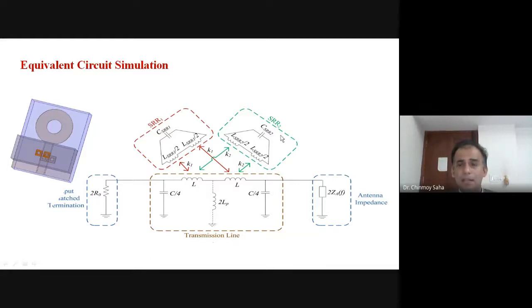That's okay. The more interesting part is this section, which is an impedance. At that impedance, you are saying 100 ohm, because another 100 ohm will come in parallel to make it 50 ohm. But actually, because it is a wideband antenna, you cannot call it a 50 ohm termination. It's a termination which is a function of frequency. That's why you see here it is not 2 Z0 but 2 ZAF, and ZAF is the antenna impedance as a function of frequency.